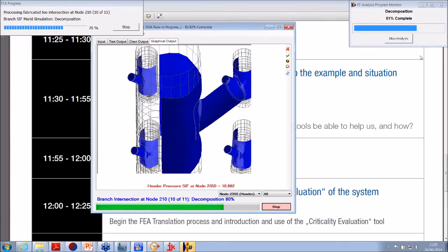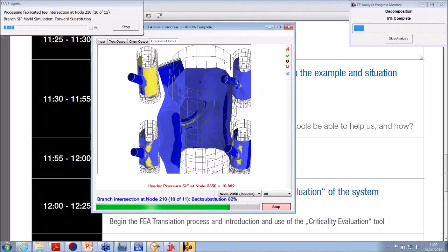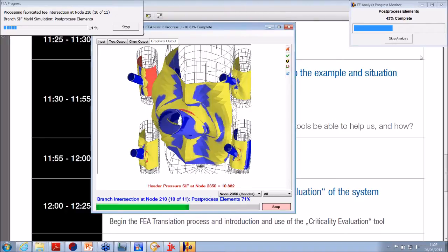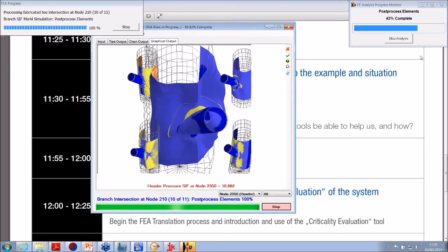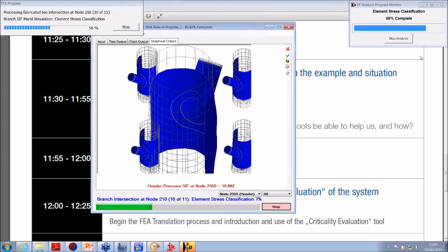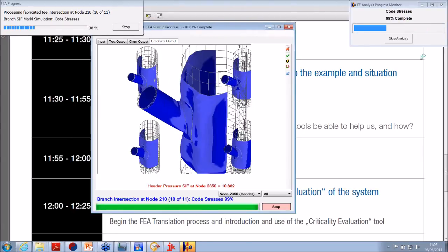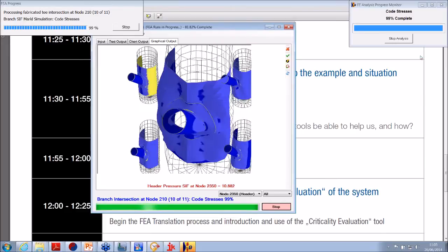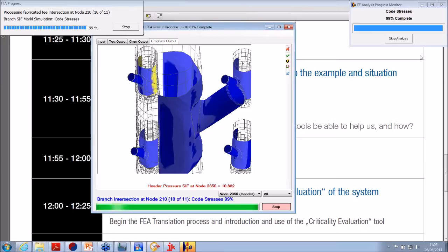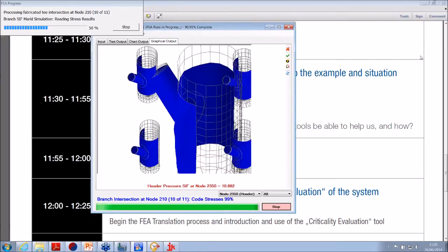In fact, in the case where you've got torsional stresses about a branch connection, B31.3 right now uses a value of 1 for the stress intensification factor. And in general, the stress intensification factor is closer to IO, the out-of-plane stress intensification factor, times the d over D ratios. So the torsional stress intensification factors, as Chris showed earlier, can be off by 6 or 7 times for large D over T branch connections.